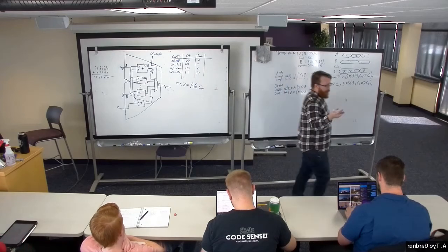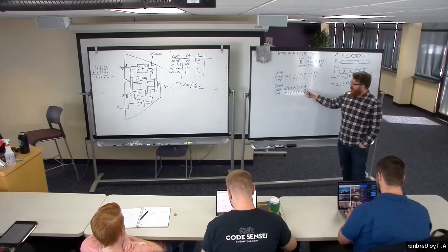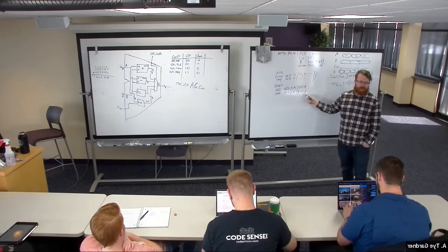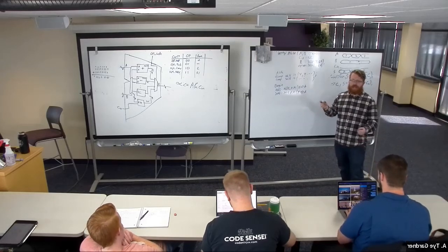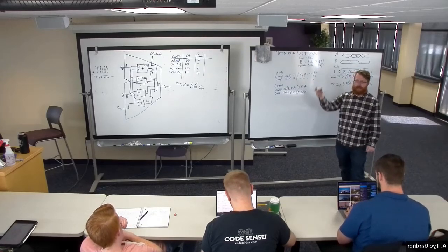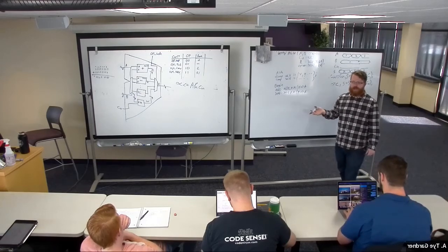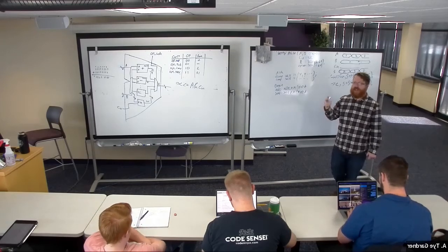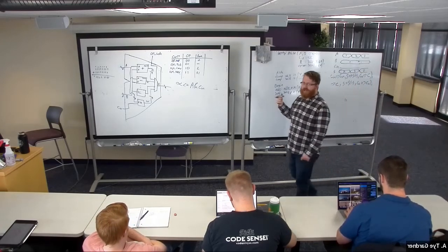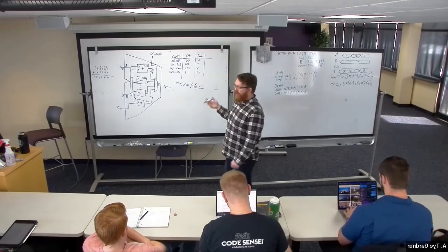So back to the original point, see how I've mapped A and A to the same thing? This is okay because these are inputs. So it's just saying that one signal can tell multiple things what to do. Just like a traffic light is an output and it can tell multiple cars that it's okay to go. However, if you have 2 signals trying to drive the same thing, it doesn't work.